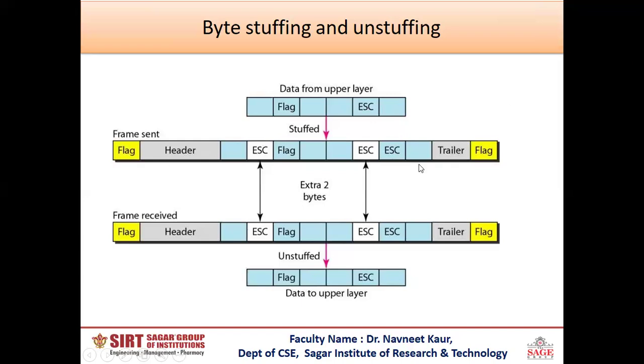Now this frame is sent, and when this frame is received at the destination, the extra ESC bytes which are added before this flag byte and ESC byte are removed from the data load.